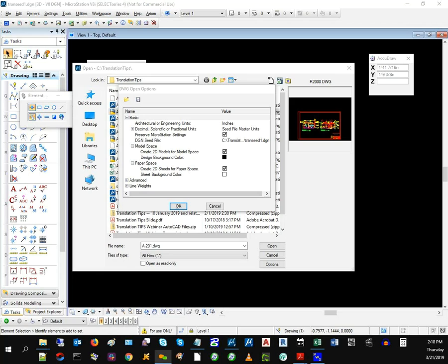And again, it's simply because in AutoCAD, when it comes to civil-oriented stuff, it's just feet is what's used, an imperial foot. But in MicroStation, it's almost always a U.S. survey foot. And so the slight differences between them, I think one U.S. survey foot is 1.00001 imperial feet. So it's not a big difference, but as you get out to thousands of yards and miles and stuff, that difference becomes very apparent, particularly when you're doing roadway projects and civil-oriented projects. So that's one thing that you need to care for related to doing translations.